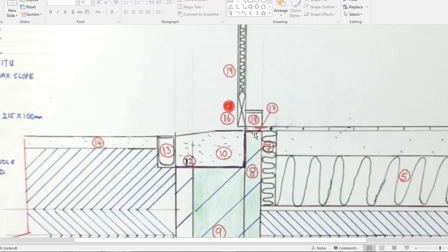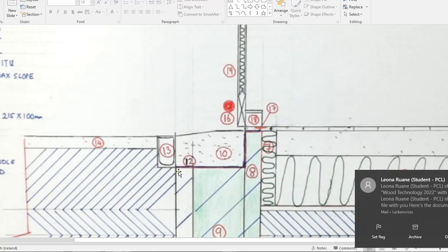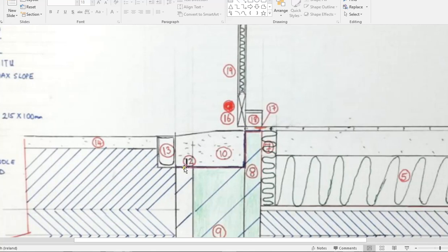The other details that we have marked in here, we have our floor. So our floorboards 25 mil in height, tongued and grooved together. We have our saddle, or door saddle, a level saddle now here for the door. And then we have our piece of skirting board put on the inner wall. So we can draw our piece of skirting on here, so that's where number 18 is here. And then what we have here is showing in blue here, along with the red line for the radon barrier, we have a blue line here also showing.